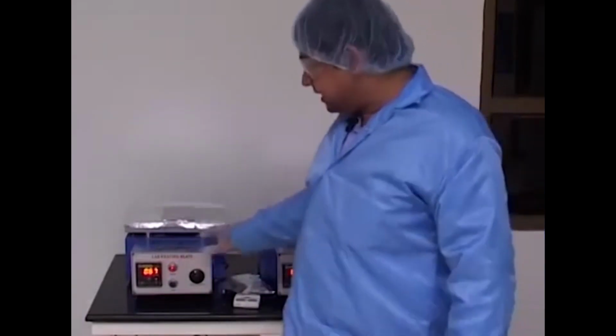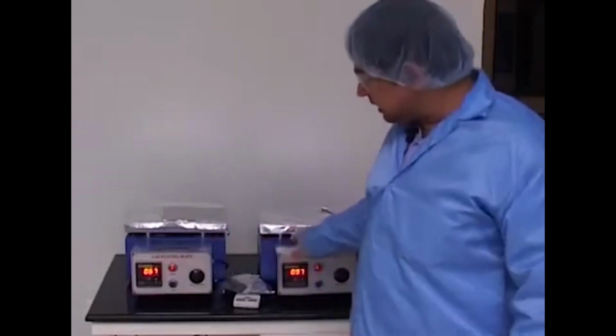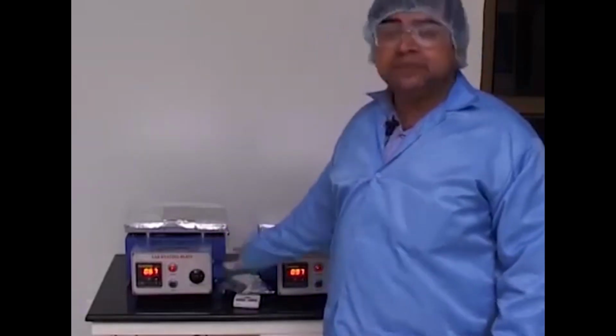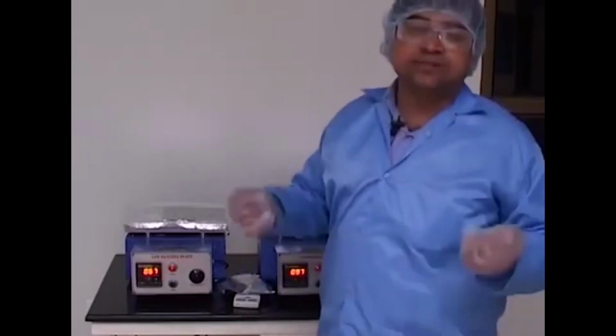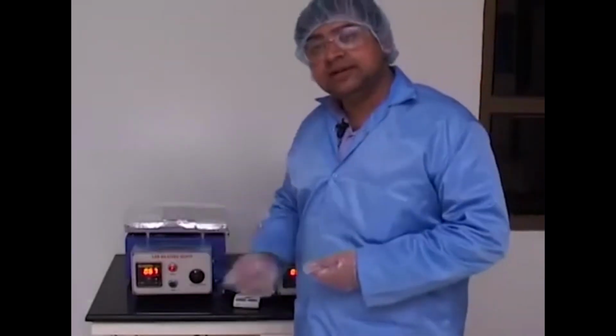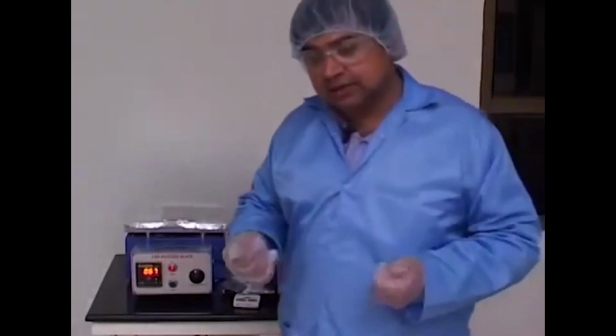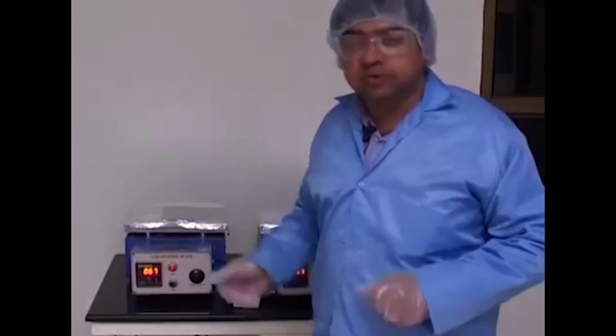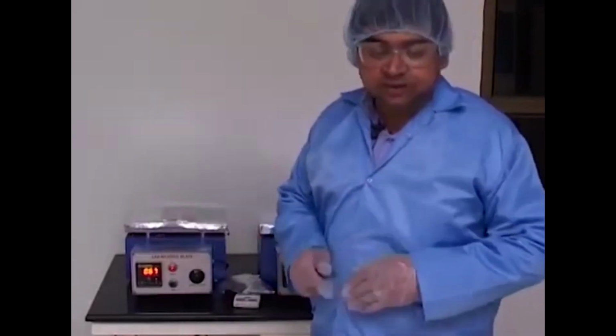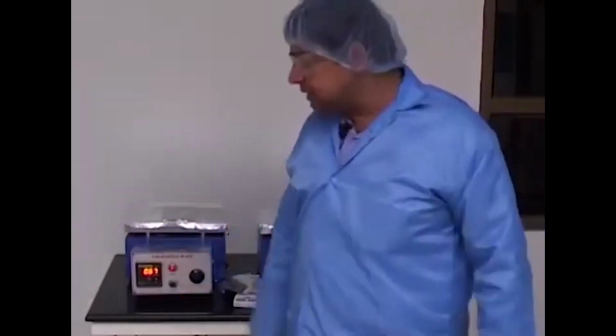So therefore we use hot plates for this purpose. Here, as you see in this particular illustration, there are two hot plates I have. They have been preset to the temperatures of 65 and 95 degrees Celsius, and each of these steps would have a certain time associated with it. So the spin coated resist on the wafer would be brought in, and these plates would be used for heating so that we can get a cured film of the resist on the surface.